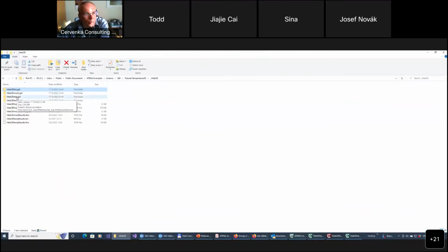And there we will import into the static model. I will show you later how exactly to do that. We will import the results from the fire analysis. And these data from the fire analysis are actually stored in some intermediary files. So that is this file and this file. BIN represents the geometry, and THW, which stands for temperature, humidity, water. So this actually contains the important data that we will later use in this static analysis.